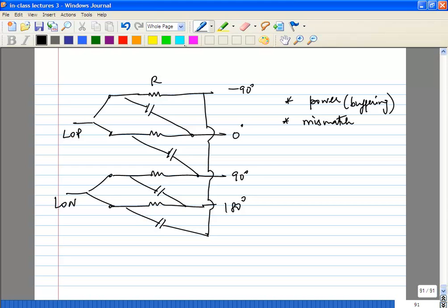And of course, the one thing you have to keep in mind with respect to power is, if you want to reduce the power of the drive, you need to increase your R. You want to make it as capacitive as possible, which means if you increase your R, your capacitance will reduce, because your RC decides what frequency you're operating at, and if you decrease your C, you become more sensitive to parasitics. You have to keep that in mind.